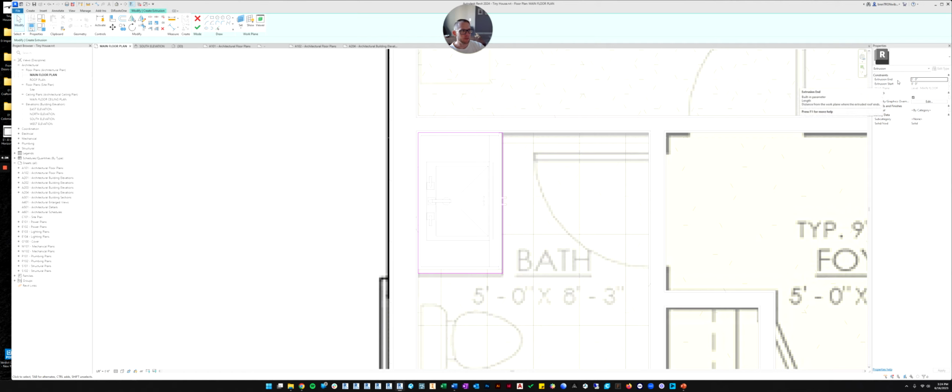And then it's going to go up 1 foot. So that's not what we want. From the floor, we want the top of the countertop to be 36 inches. Or at least that's the cabinet we chose. If you remember when we chose the cabinet, we picked a 36-inch high cabinet.